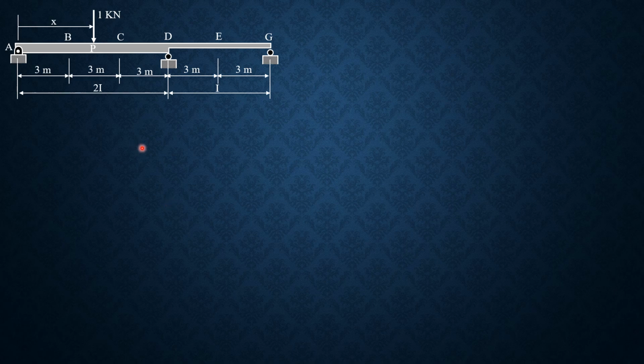So we have Ay here. Let's draw the free body diagram from A to C, and the unit load will be up to 6 only. So this is the positive shear at C, positive moment at C. So for maximum Ay, we sum up.